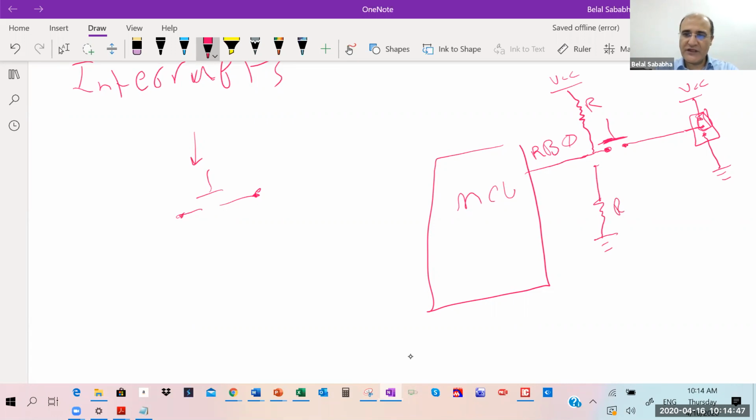So here is another, if you want to draw it correctly, it's another jumper actually, or a dip switch, but you can choose to slide this high or low. So scenario 1, if this is pulled to high, then when you push, you need to connect this to ground, right? So scenario 1 is what I'm drawing around in blue.